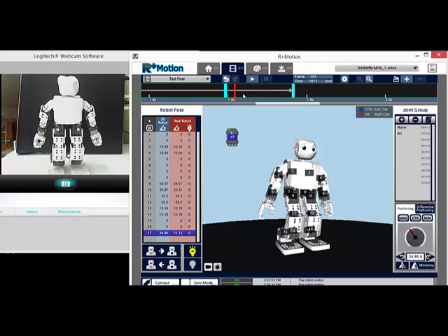Okay, so let's see, 1625. That's easy this way. Frame 207 is 1617. Okay, see, 208 is 1625. So you can see that between two frames, when you check on it, it bounces around between 7 and 8 milliseconds. And this is interesting because this is the delta time, or the time interval, at which every Dynamixel got refreshed, shall we say.